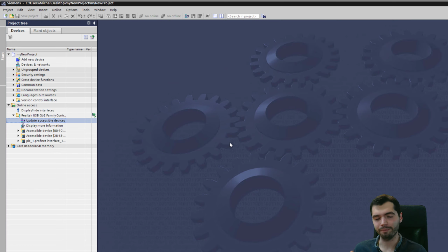It will be broadcasting messages using MAC addresses. So if you are using VPN, for example, this will most likely not work for you because most VPNs use just layer 3. They don't allow for layer 2 communication on the MAC level, while PROFINET is MAC based, okay?